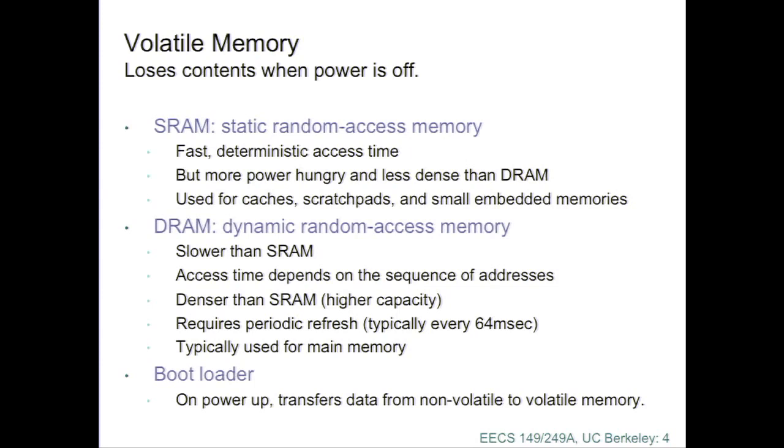Static RAM is different. The access times are predictable, controllable, but it's a much more expensive memory technology. So in the circuits, a dynamic RAM is typically implemented with a single transistor today. Static RAMs are typically implemented with at least 6 transistors. So they're quite a bit bigger in area, which means that on a given region of the die, you can't have as much memory.